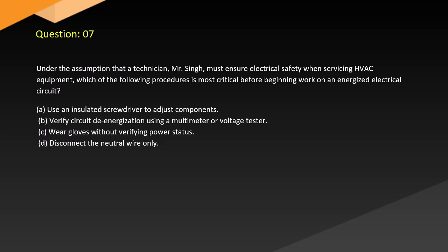Question 7. Under the assumption that a technician must ensure electrical safety when servicing HVAC equipment, which of the following procedures is most critical before beginning work on an energized electrical circuit? A. Use an insulated screwdriver to adjust components. B. Verify circuit energization using a multimeter or voltage tester. C. Wear gloves without verifying power status. D. Disconnect the neutral wire only.